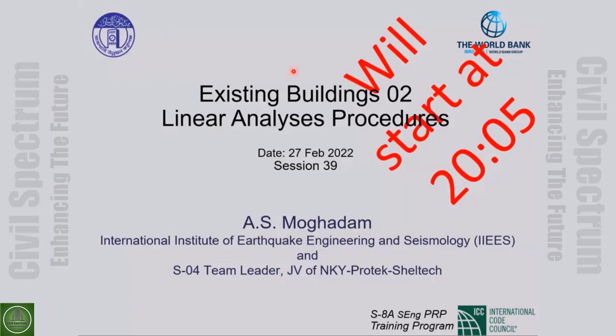When we look at the design procedure in BNBC for the seismic design of new buildings, we saw that the main point is the R factor. For new buildings, we can control how good the supervision in the field is, and that detailing can be applied and implemented in the building.